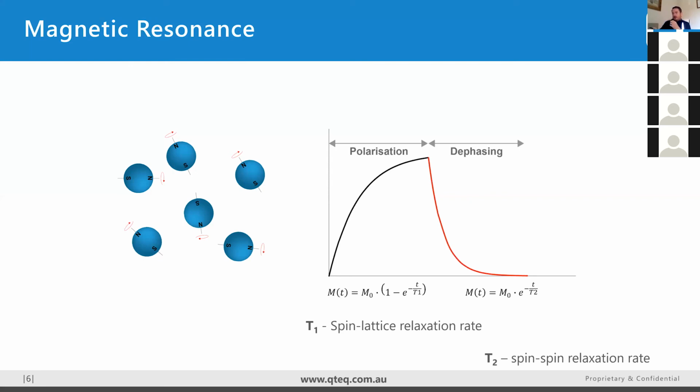Yep. So the last question. When you're averaging, if we think of a nice layered formation where we have layers on top of each other like this, if we do the arithmetic mean, we end up with our average horizontal hydraulic conductivity.